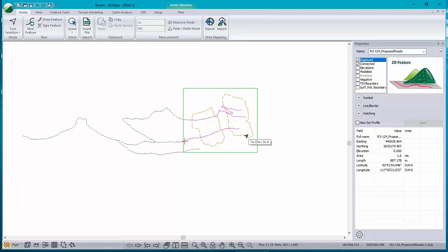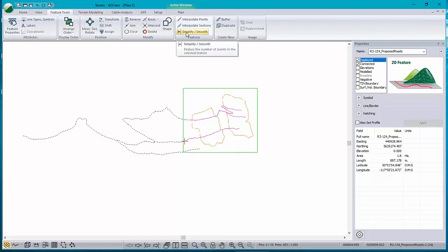That's quite a lot of points, and I could use these features right now to insert my LiDAR and use these to define corridors. But here's a little trick. If you are defining a corridor, and you'll see what I mean in a second, for thinning your LiDAR to an area of interest, it's smart to first make sure that you have a relatively simple feature.